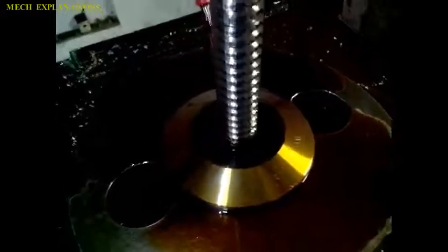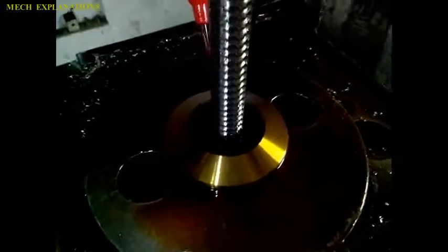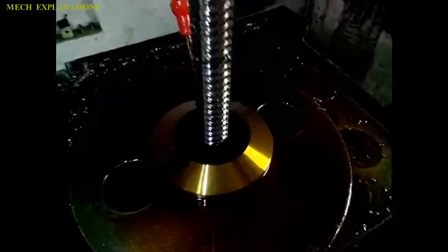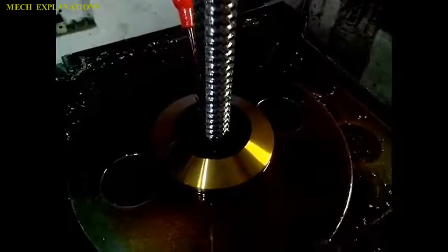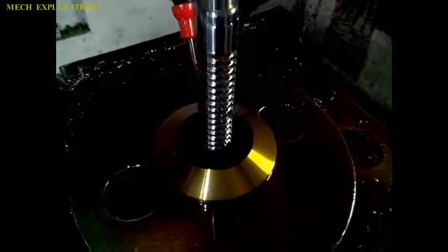Typical workpieces include small to medium-sized castings, forgings, screw machine parts, and stampings. Even though broaches can be expensive, broaching is usually favored over other processes when used for high-quantity production runs.